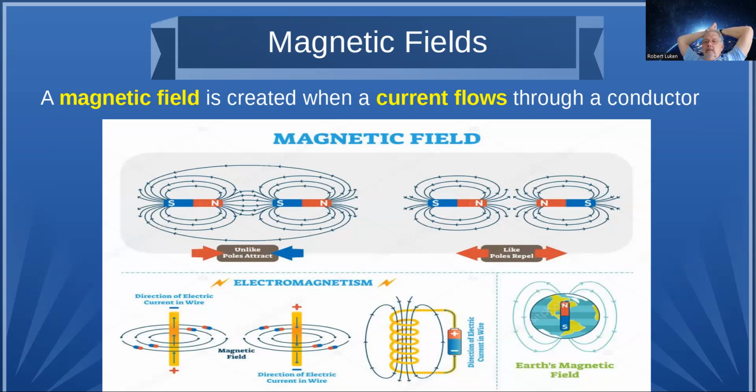As the charge builds up, the more energy we store in that field, the voltage is building up and the current is therefore decreasing, because it's a function of the difference between the applied voltage and the voltage across the plates of the capacitor.